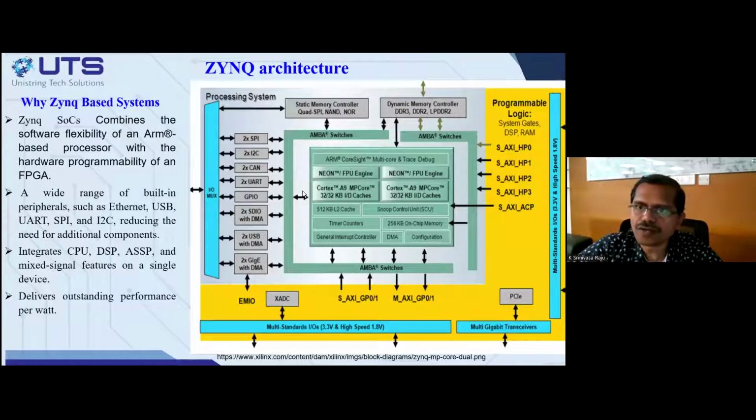Okay. Now with this background, if you see this diagram, you can see that this complete thing is a Xilinx chip, the Zynq chip. You have this core here, which is an ARM processor core. This ARM processor is similar to any ARM chip that is available in your mobile phones or anything. It is a hard core. Then you have standard peripheral control blocks. You can recollect all these are peripheral control blocks. Then you have the PL logic.